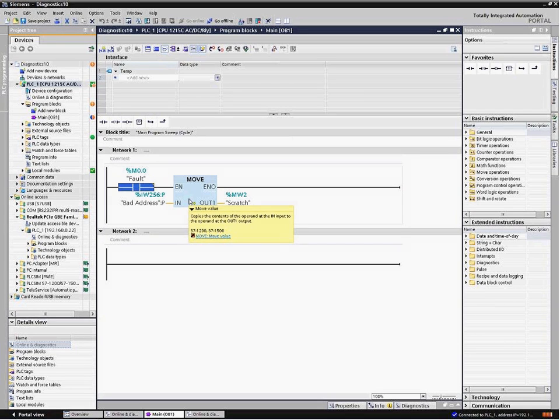Okay. Now, there are some other neat features to this. The diagnostic buffer is available to us in several different forms. Oftentimes it's local, but we can access this remotely. This is something we can do over the internet if we have access to the PLC. Another way of doing this same thing is to put this diagnostic buffer on the built-in PLC web page, which is fairly straightforward to activate, and then we would have access to the same data we just looked at.